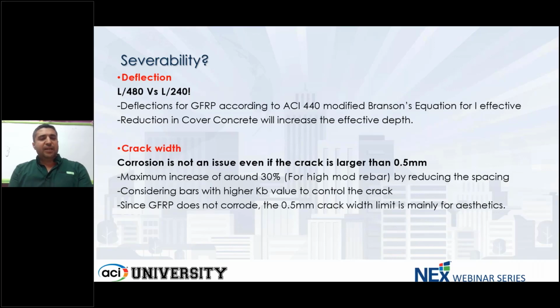That was it. So really, when you think about deflection and crack width, there are many ways to go around it, as long as you're using a high modulus and good quality rebar. The other thing that I have to mention, really, what's interesting is many structures that are out there are already over designed with steel. I'm not using the terminology over design. I'm going to use the terminology over safe design. That means that the structural engineer was designing this based on number 4, and for a factor of safety is putting a number of 6 in there. When you convert some of those designs from existing steel design to fiberglass, you will actually see that the amount of reinforcement won't change, and you are within the limits of L over 240, L over 360, L over 480. So food for thought, just keep in mind, don't look at it as, oh, I need significantly more reinforcement. Do the calculation and verify how much more you need, and you will be surprised to see that you don't need much.